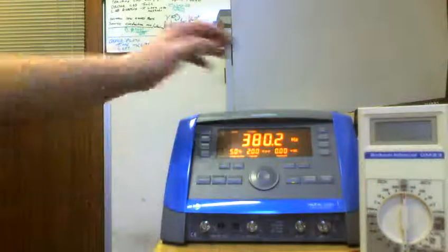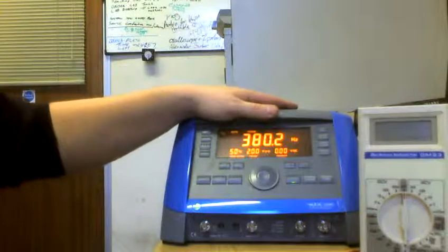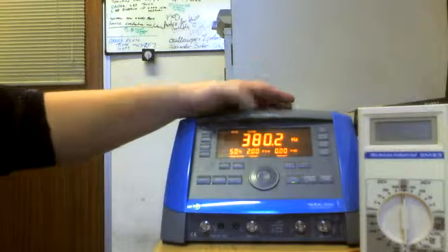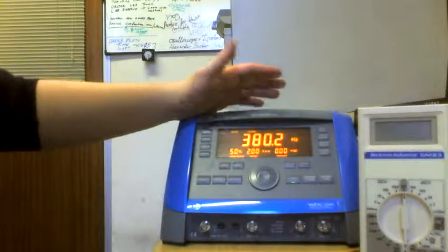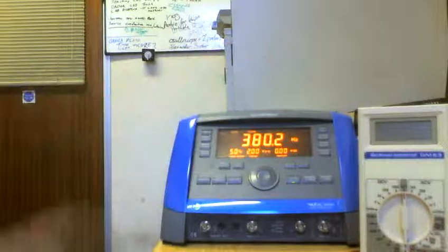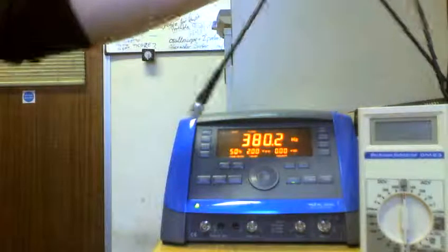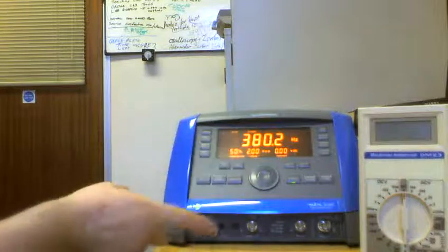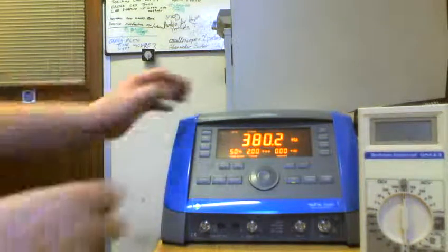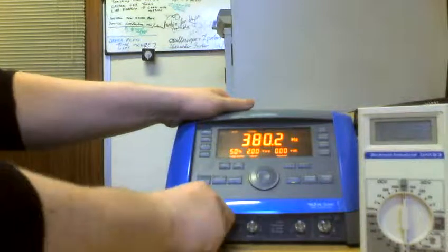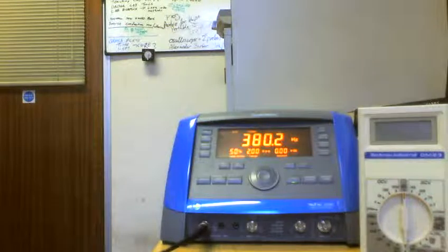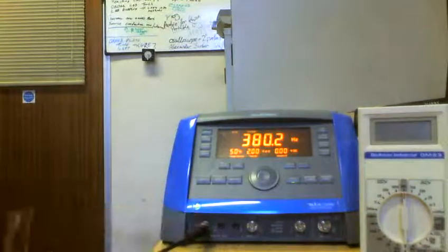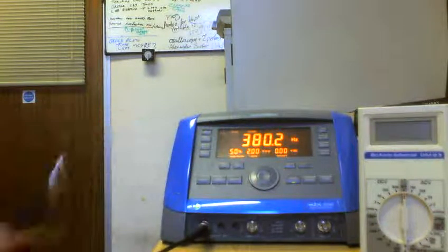Right then, here we are. Got our signal generator here. I just switched this on, it's currently set to 2 volts peak to peak, giving out a sine wave of 380.2 hertz. Let's see what happens when we try and read the output. We've got the main output down here, so connect our BNC cable to this. I'm not using the multimeter probes because it can be a pain trying to probe inside a BNC socket, so I've got a BNC cable to some 4mm plugs.